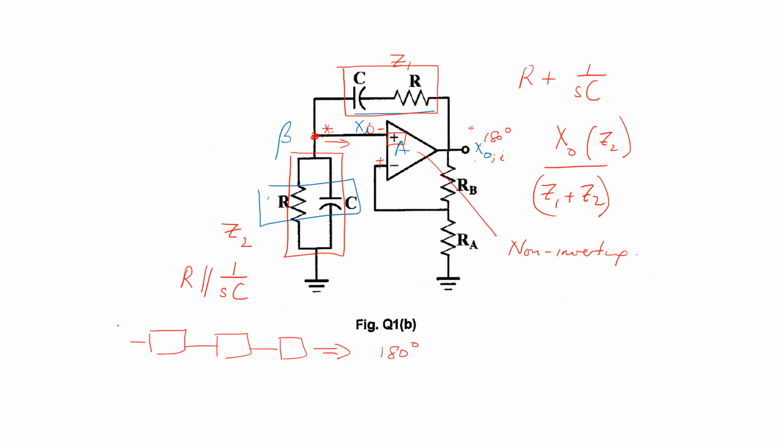In other words, if I had a V in here, what I had coming out was a minus V. Then we sent it to an amplifier with a negative gain, a gain of -1, so that when you got out here, you had plus V in coming back out. So if the amplifier gave you the other 180 degrees, in this situation we would have used an inverting amplifier.